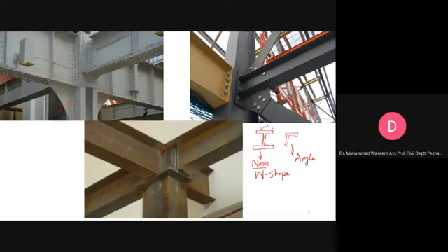have to select these shapes, but these shapes need to be connected. Okay, so they are connected by bolting, by welding, or by riveting. Please remember that riveting is a permanent fastener. Bolting is like you can replace this bolt very easily. And the advantage of using welding is that it makes a bolted or riveted connection look much simpler, and less steel is used in welding compared to bolting and riveting.